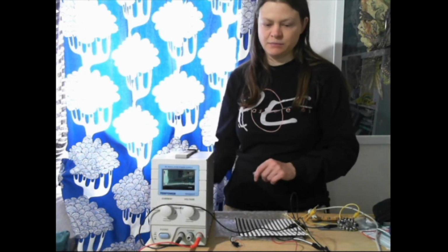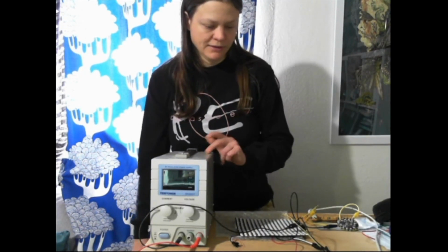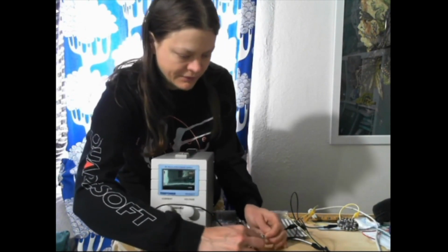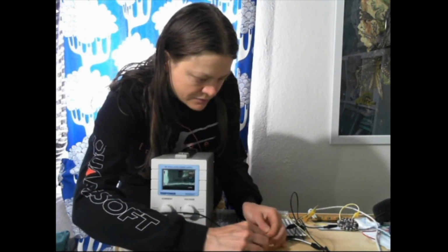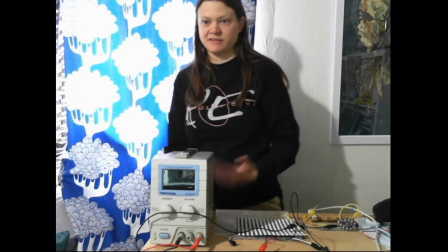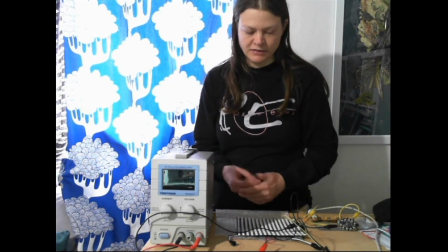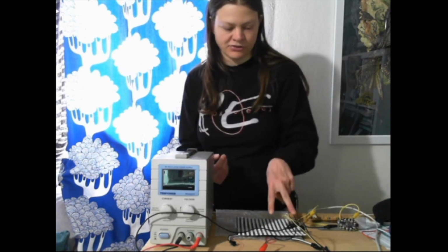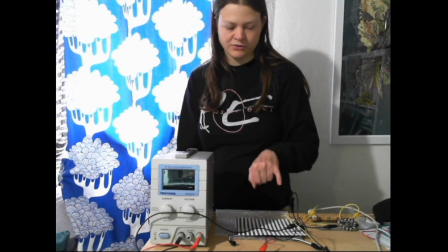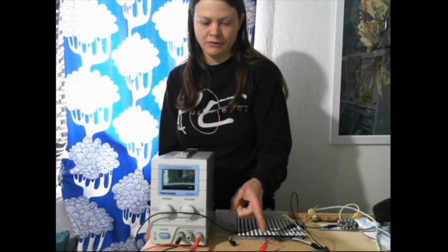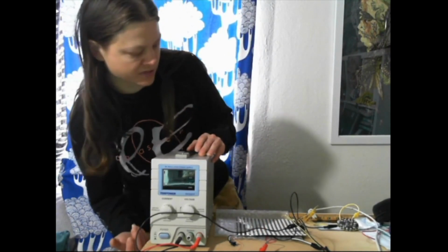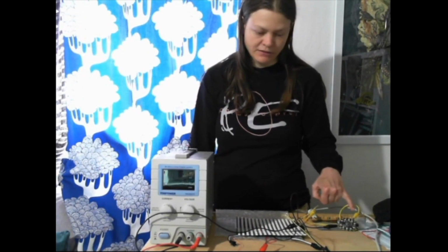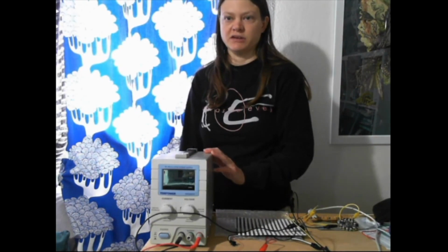Then once you get that, the last step is to connect the power from the power supply to this 5-volt pin on the middle of the matrix, like so. And at that point, that's the 3 connections. You've got 3 grounds. The one from the circuit playground and 2 on the matrix are tied to ground on the power supply. You've got power on your matrix connected to power on the power supply, and you've got pin A1 run into data in on the matrix.